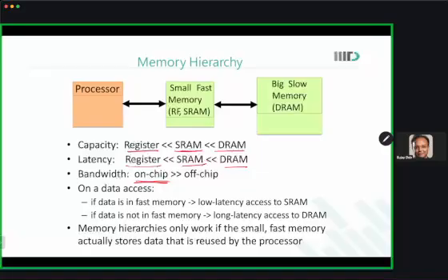So it's not directly register based memory. You can improve or make your caches, the architectures of the memory, much more efficient. So all these things are done. Even in some cases, maybe you want your first level cache, instead of SRAM based, you make it, let's say, register based, or SRAM with some tweak in it so that it performs even faster.